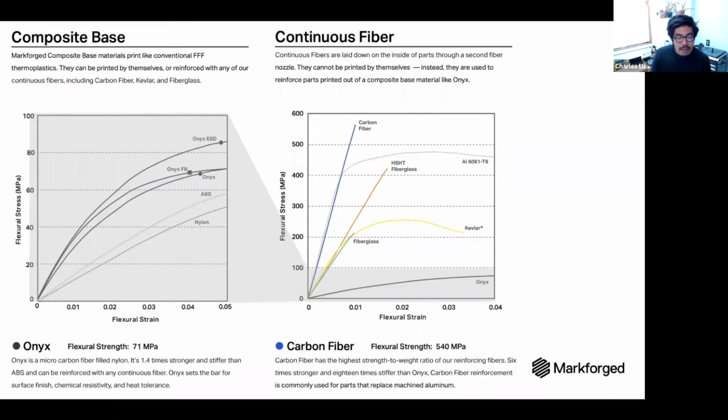What applications? It's a nylon material, so you're going to need some coating if you want it to maintain rigidity. The good thing is the continuous fibers inside the part tend not to lose so much strength. So once you put the fiber in, and then you coat it with, say, a polyurethane or like an acrylic varnish, you should be okay for some wet application, at least for some time.